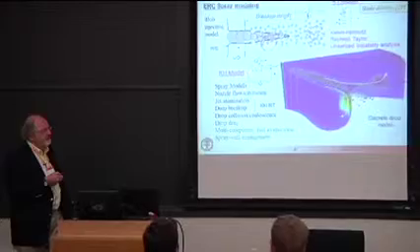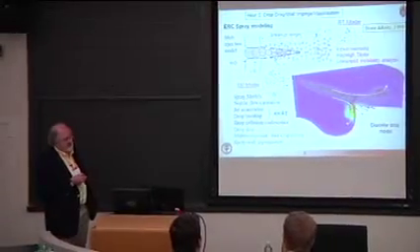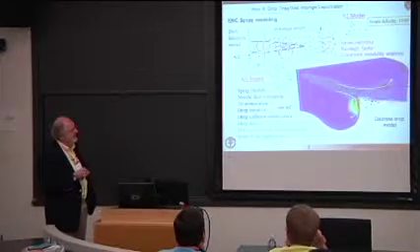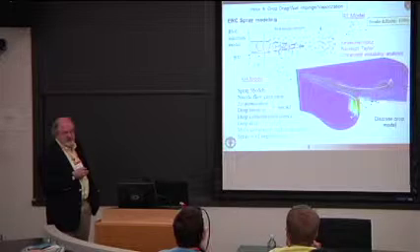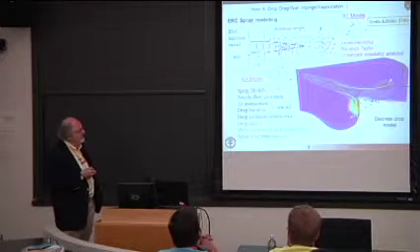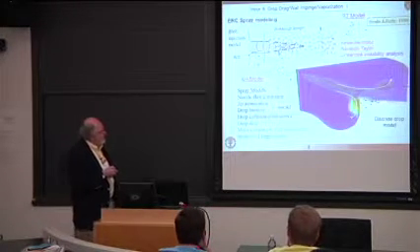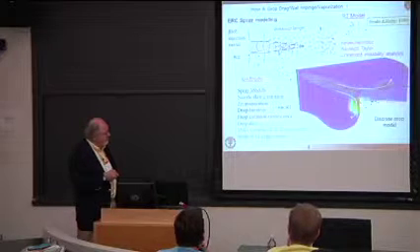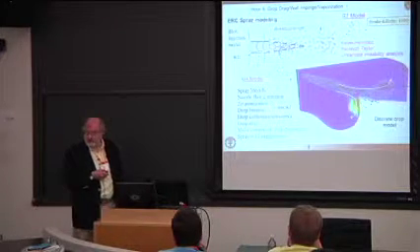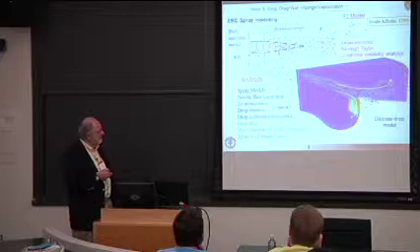Once the droplets are formed, they then undergo Rayleigh-Taylor breakup due to this great, in this case, deceleration that they experience as they're injected into the high gas density environment. In addition to the breakup, they undergo collisions and coalescences and so on.